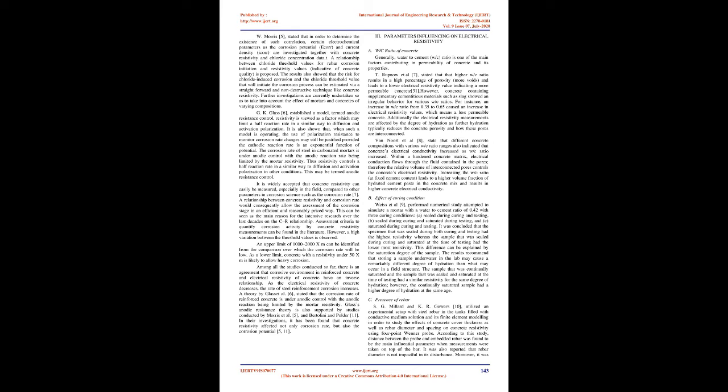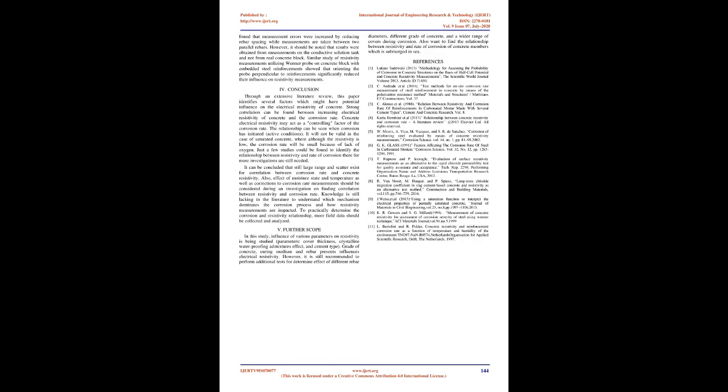Van Noort et al. [8] state that different concrete compositions with various W/C ratio ranges also indicated that concrete's electrical conductivity increased as W/C ratio increased. Within a hardened concrete matrix, electrical conduction flows through the fluid contained in the pores, therefore the relative volume of interconnected pores controls the concrete's electrical resistivity. Increasing the W/C ratio, at fixed cement content, leads to a higher volume fraction of hydrated cement paste in the concrete mix and results in higher concrete electrical conductivity.